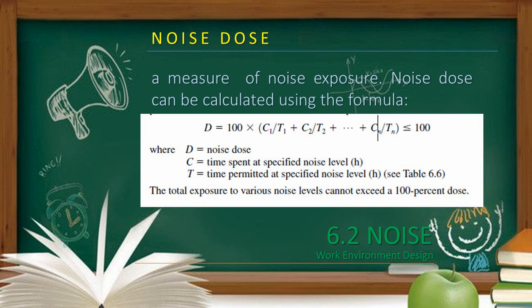Today, OSHA, or the Occupational Safety and Health Administration, also requires a mandatory hearing conservation program, including exposure monitoring, audiometric testing, and training, for all employees who have occupational noise exposures equal to or exceeding a TWA, or time-weighted average, of 85 decibels. Although noise levels below 85 decibels may not cause hearing loss, they contribute to distraction and annoyance, resulting in poor worker performance. For example, typical office noises, although not loud, can make it difficult to concentrate, resulting in low productivity in design and other creative work.